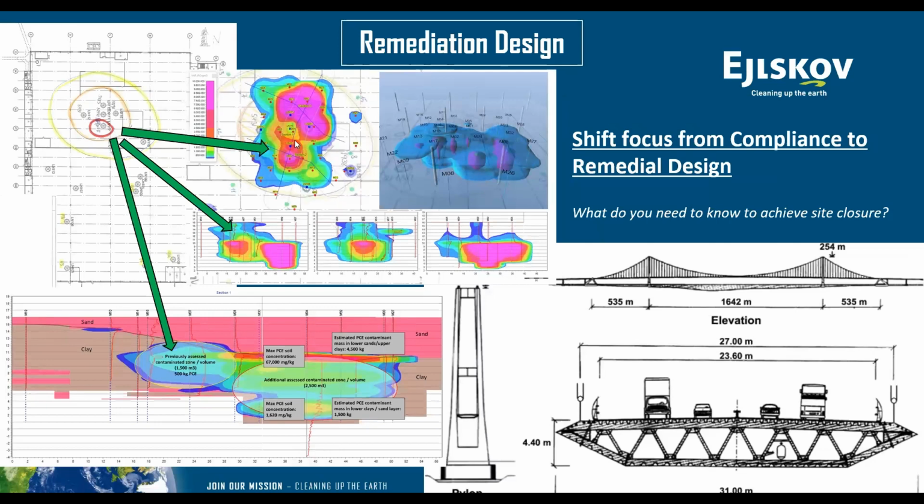And that guidance from the MIP allowed us to then go and collect all the necessary soil data at high resolution to be able to create a fine-tuned CSM and mass model, as we can see below, where the signal of the MIP is now quantified by, probably in that case, 300 plus soil samples. We could see that there was a clear layer of DNAPL causing the problem at the site, which could not be resolved until then.